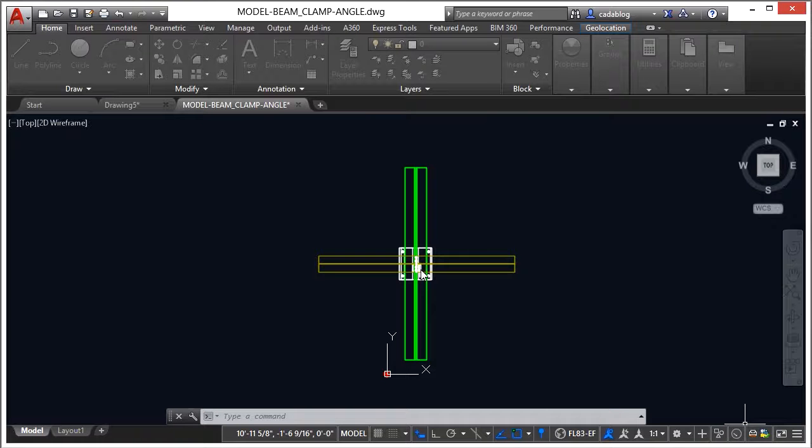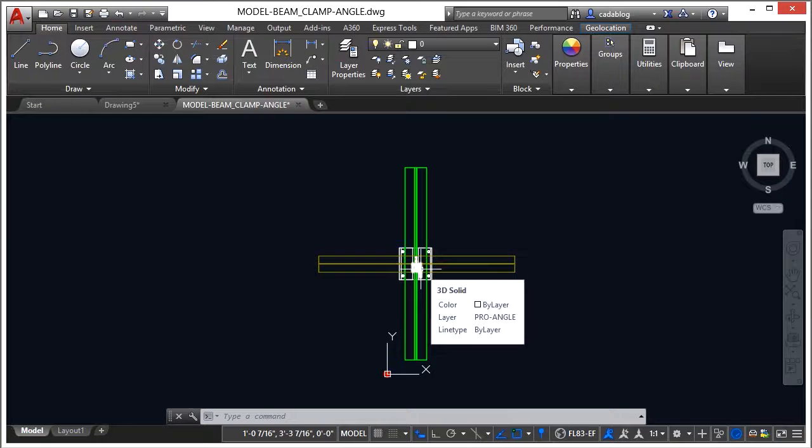Another thing that they've changed, line types with dash and dot combinations, they'll display as round dots. Another subtle but useful improvement is the ability to select or snap to the gaps on those objects. Before you couldn't do that. You can also turn that off if you want to by typing in LT gap selection. It's a system variable. You can turn it off or on.